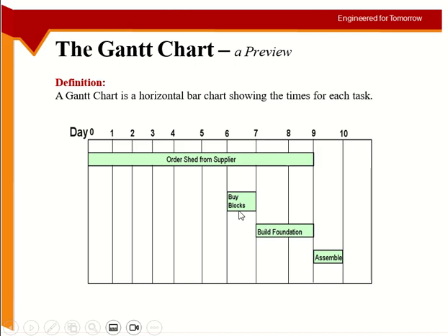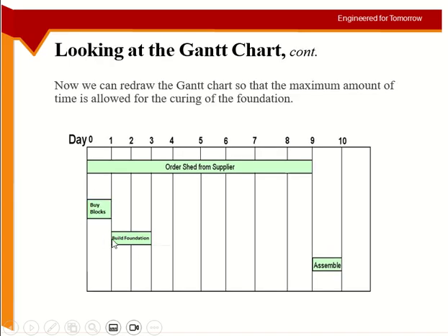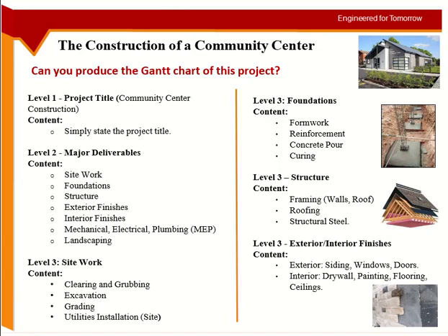We want to buy the blocks just before building the foundation, so we don't have to store them for many days. This was the storage linkage here. But the shifting of these two activities to here was because of curing. Buying the blocks just before building the foundation was to avoid storage for longer times. So this is the storage story here.